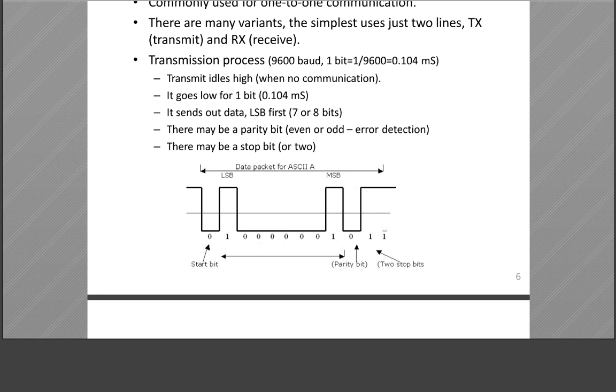For example, if we had 5 ones in our data, for example 1 0 0 1 1 1 1 0, that is 5 ones. This is an odd number. Then P must be 1. All of them is 6 and is even. That's right.